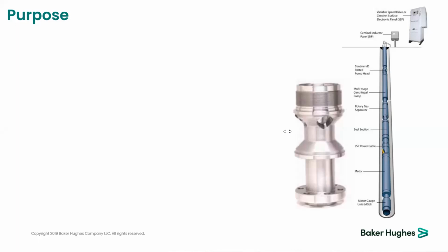The reason for that will be wrong installation, either during workshop assembly or field assembly. Either it was missed altogether during assembly, or it was installed in a wrong way due to the shimming calculation, which we explained. There is a shimming procedure that should be followed and calculated properly in order to avoid going above the required value of shimming, which is called over shimming, or below it, which is less shimming.